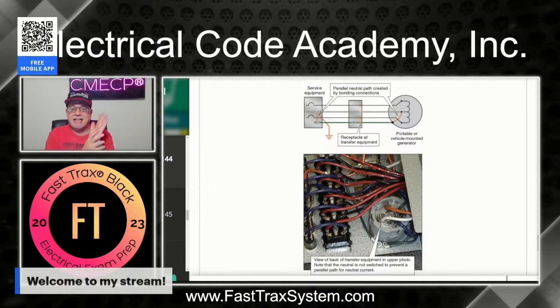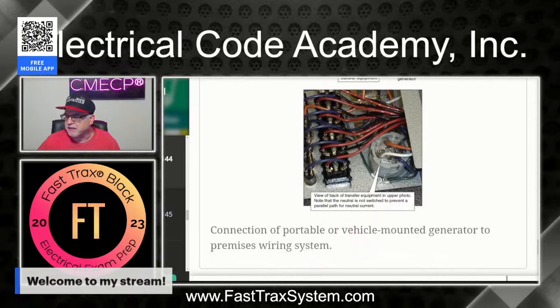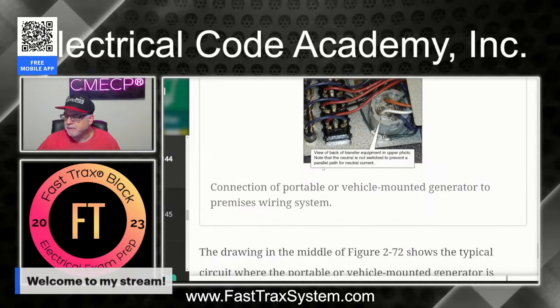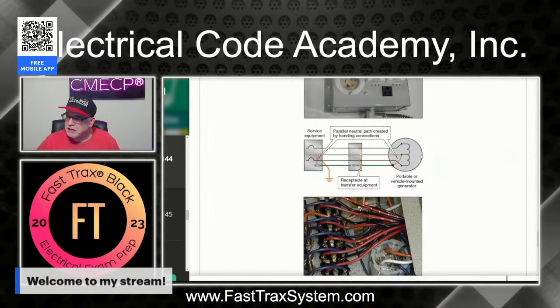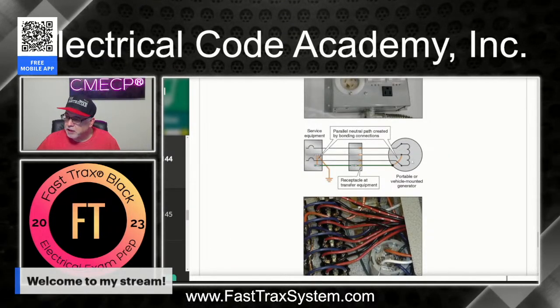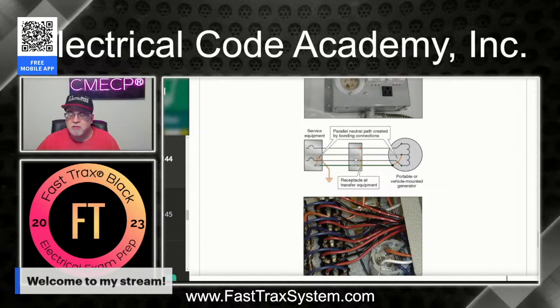And now I'm not going to get into modifying generators. We'll leave that for you to search out and find for yourself. I'm not going to get into that liability trying to explain that here. But okay, just be careful and realize that if you're going to use a generator that has the neutral connected to the frame, which is what you would use in a standalone, and you're going to use it in this scenario, you need to what?